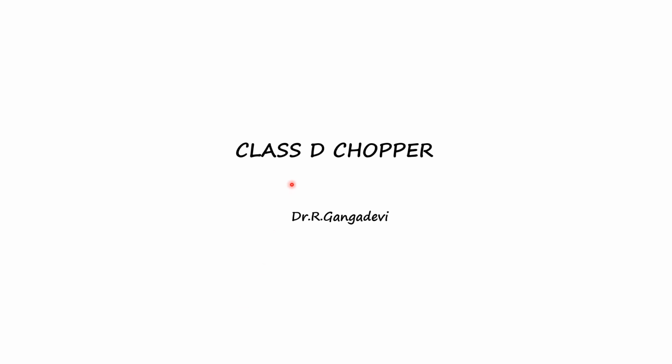Hi everyone, in this lecture we will see the operation of class D chopper. A class D chopper is a two-quadrant chopper which can operate in first and fourth quadrant of output voltage and current plane. So in this chopper, the power can either flow from source to the load or load to the source depending upon the quadrant of operation.